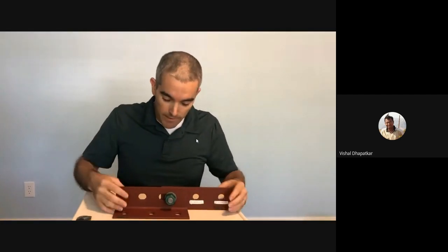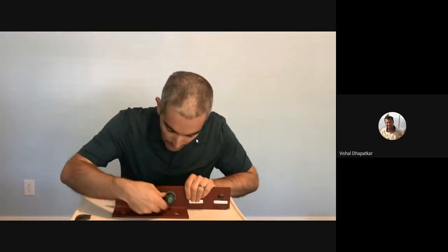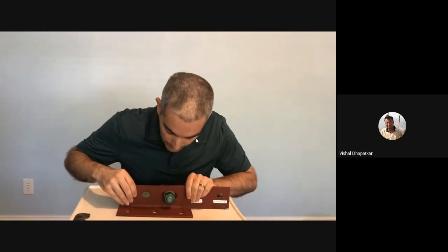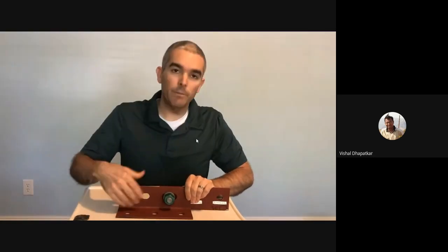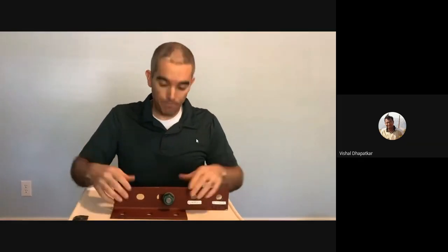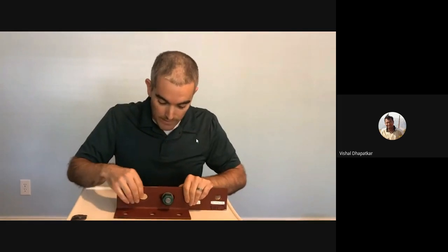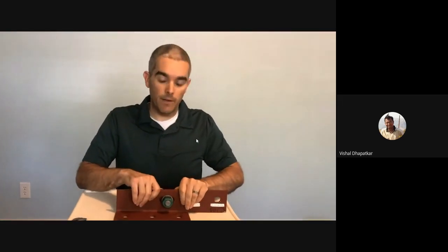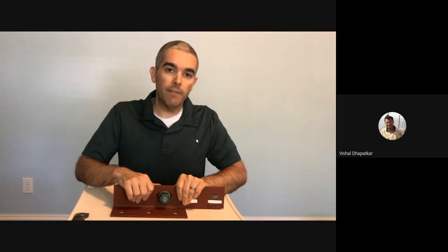So in a slip critical connection, rather than putting our bolt at the end here, what happens if we put the bolt in the middle? Well, if it's not tightened, then it'll slide. So that's what's meant by slip. In a slip critical connection, we don't want that slip to occur. The way that we're going to prevent that from happening is by tightening this bolt.